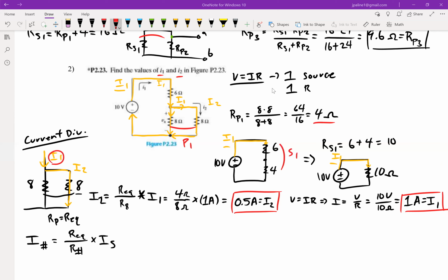And just an interesting little topic before we do, I guess. Looking at that KCL, we've got 1 amp coming in, right? Then we said we had that 0.5 going down to the right. So what will this one be? If we do some entering, some leaving, 1 amp is equal to 0.5 plus the question mark. So therefore, question mark is equal to 0.5 amps.